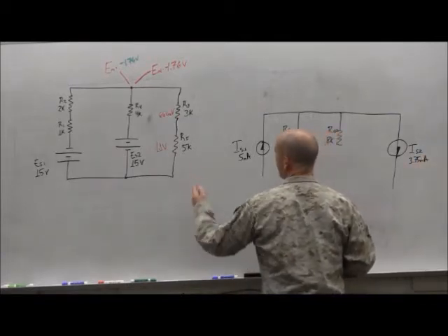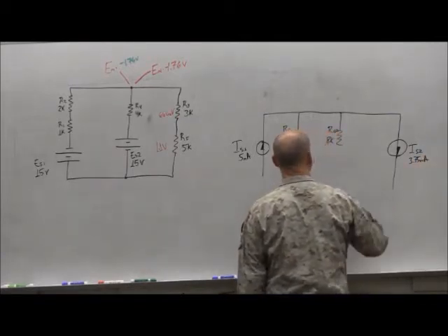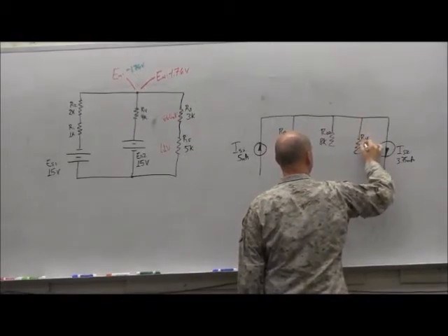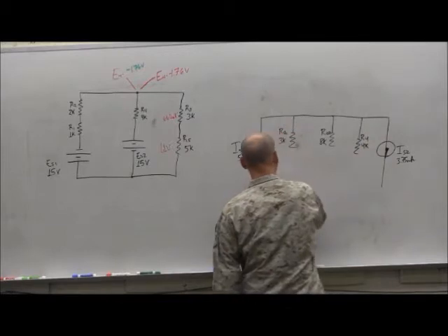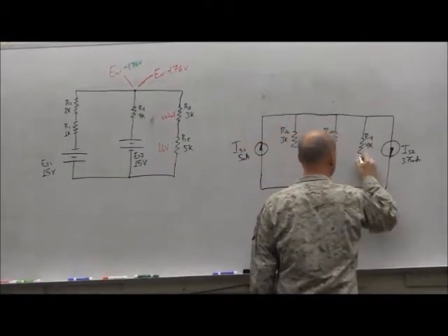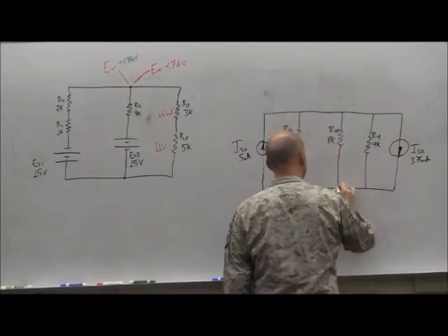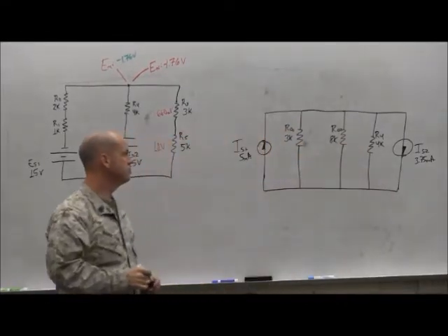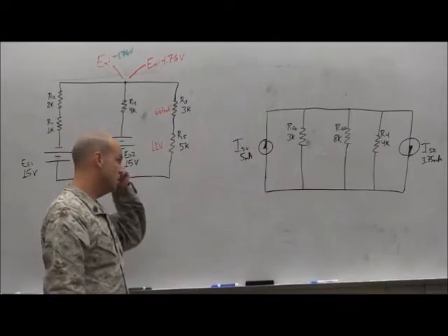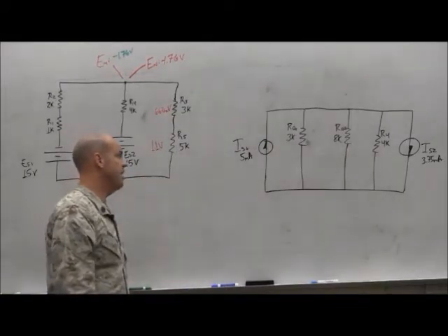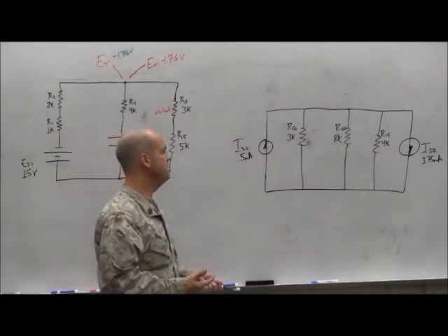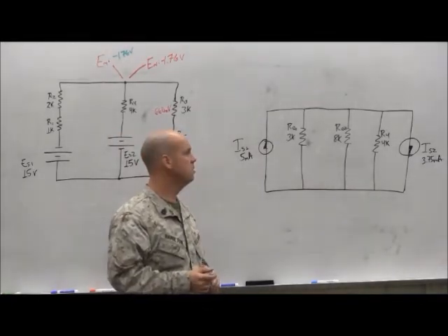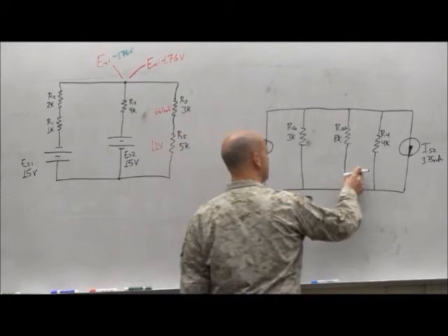What happens to that R4 resistor? Shunts it. Okay, now what do I do? Combine all the resistive values. Okay, what's the easiest way to do that? Just do product over sum, product over sum. All right, let's do product over sum here first.